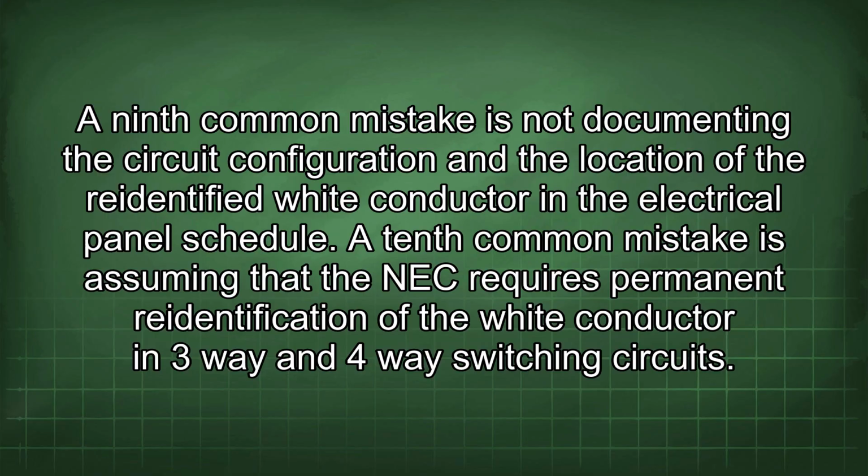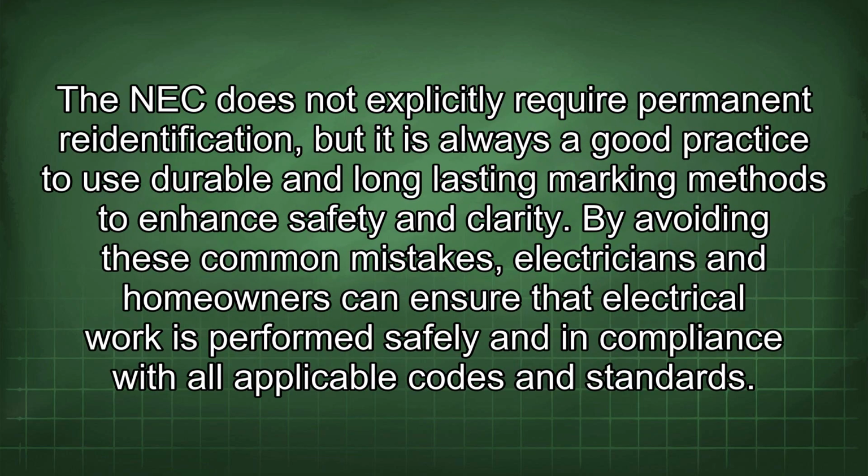A 10th common mistake is assuming that the NEC requires permanent re-identification of the white conductor in 3-way and 4-way switching circuits. The NEC does not explicitly require permanent re-identification, but it is always a good practice to use durable and long-lasting marking methods to enhance safety and clarity. By avoiding these common mistakes, electricians and homeowners can ensure that electrical work is performed safely and in compliance with all applicable codes and standards.